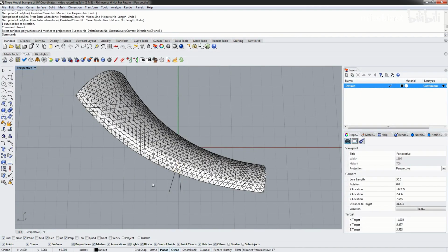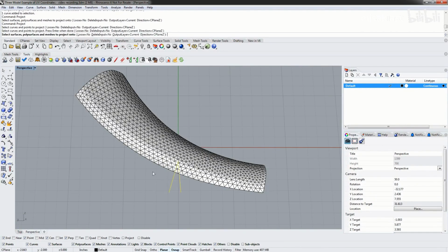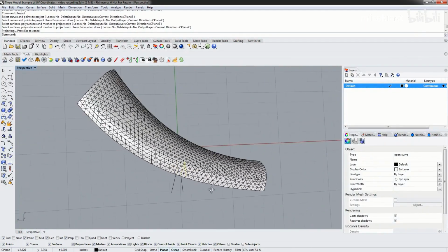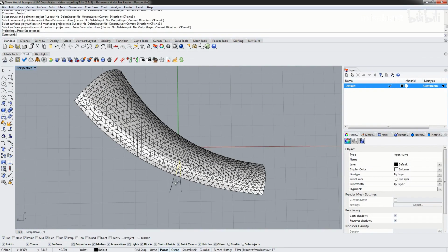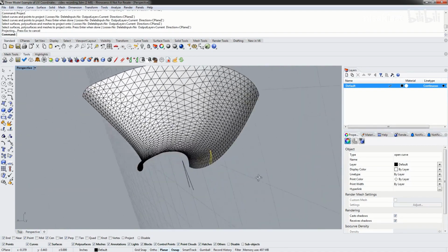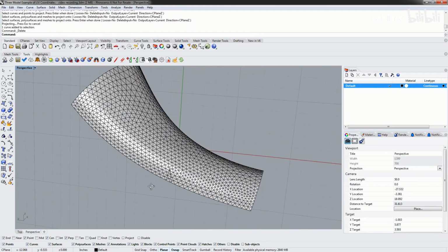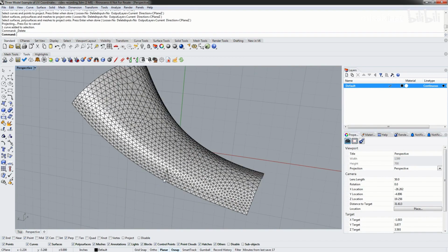onto this mesh here. So we'll use the project command, select our curve, press enter, and project onto this mesh. Rhino is going to project this curve along the viewing direction of the construction plane directly onto the mesh. And now if we rotate, we can see the projection of that curve onto this mesh. The same method can be used to create curves for use with the ExactFlat curve cutter, or in this case we're just going to use simple Rhino commands.